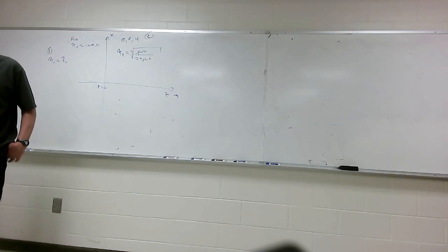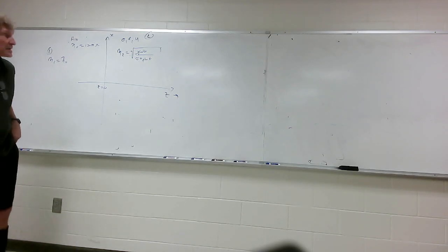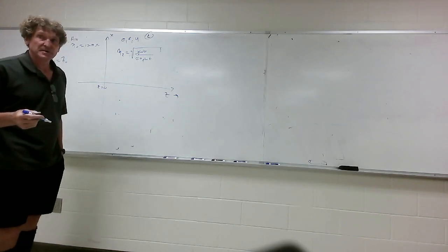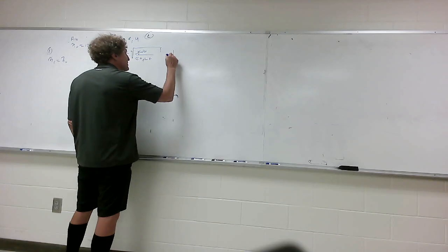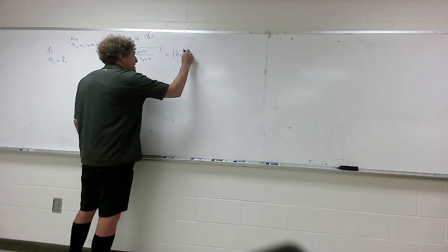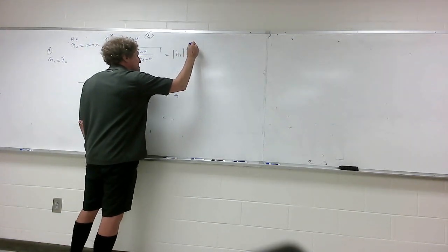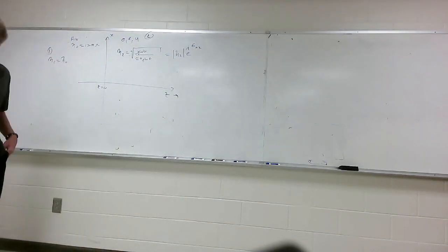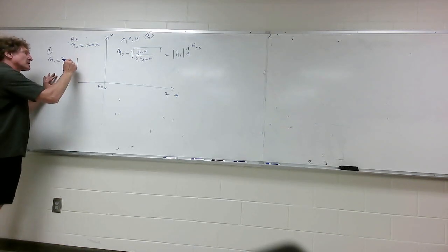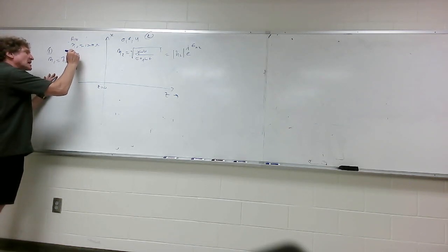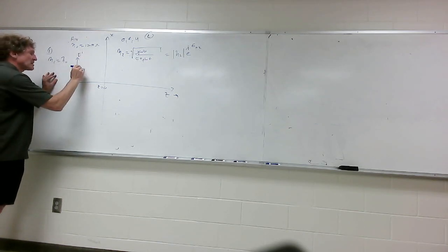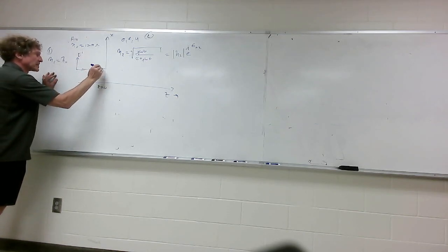That's the definition of the intrinsic impedance. And we're going to do this in phasor form. We don't know what it is, but it's going to have some magnitude of eta 2 and e to the j angle of eta 2. We don't know what it is. Now, we're going to assume we have a propagating wave over here. It's an incident wave, so it's going to have an incident electric field. It will be in the x direction, and it's propagating into this boundary, and it's going to hit it.